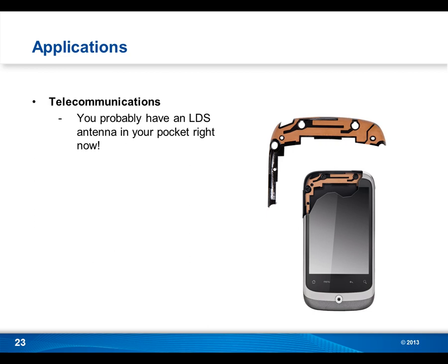So we started to wrap these antennas around all kinds of areas, and in order to do this efficiently, an MID or a molded interconnect device is really the only way to do that, because again, as we talked about earlier, a flex circuit starts its life as a 2D part, so it can't really be bent around what we call a double curved surface or sphere or something. So again, from the mechanical properties, an MID is a very attractive solution for these types of things.